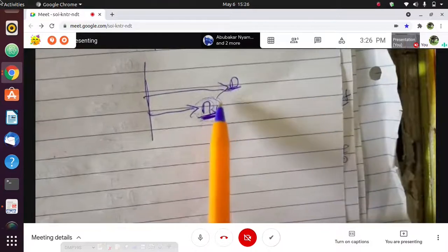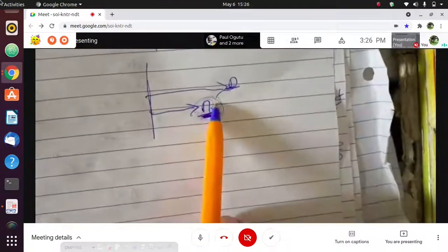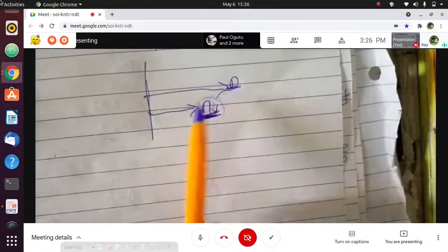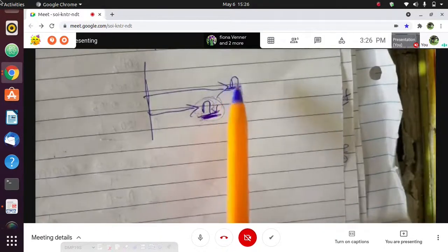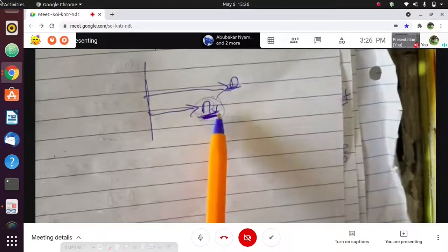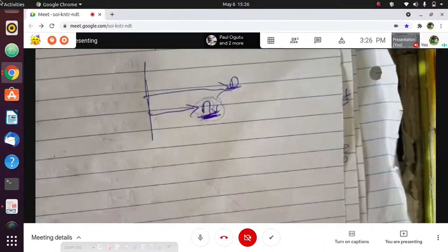This speed will be greater than this because of inertia. When you reduce this, it will reduce instantly, but because of inertia, since the rotor is already rotating, it will not stop immediately. As a result, the generating action of the induction motor will cause power flow to reverse, and the kinetic energy of the system will be fed back to the supply.